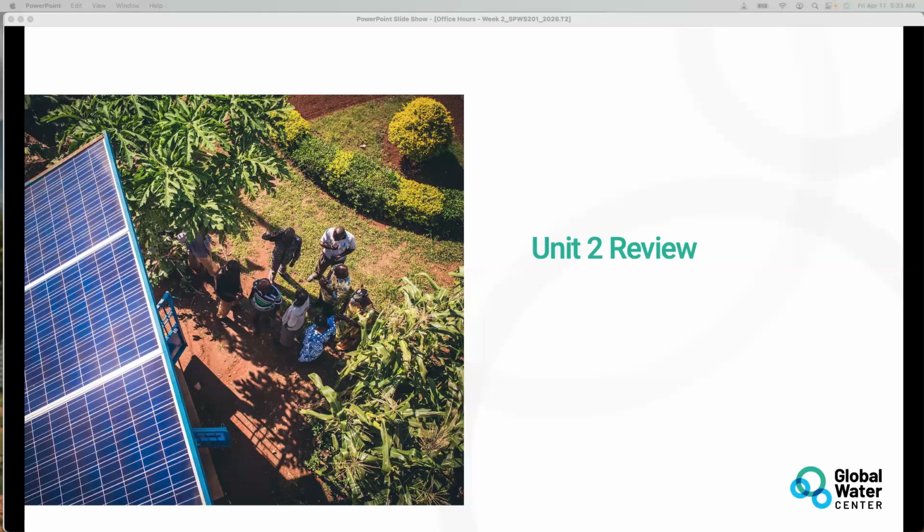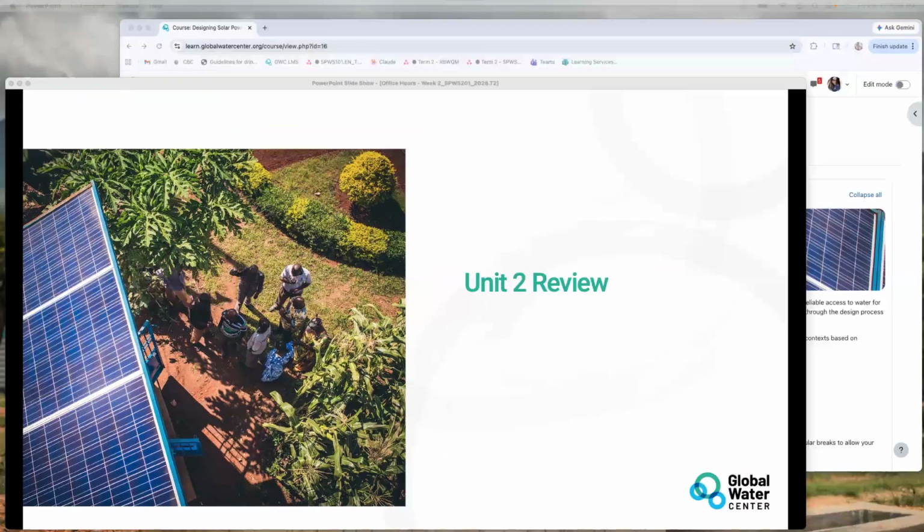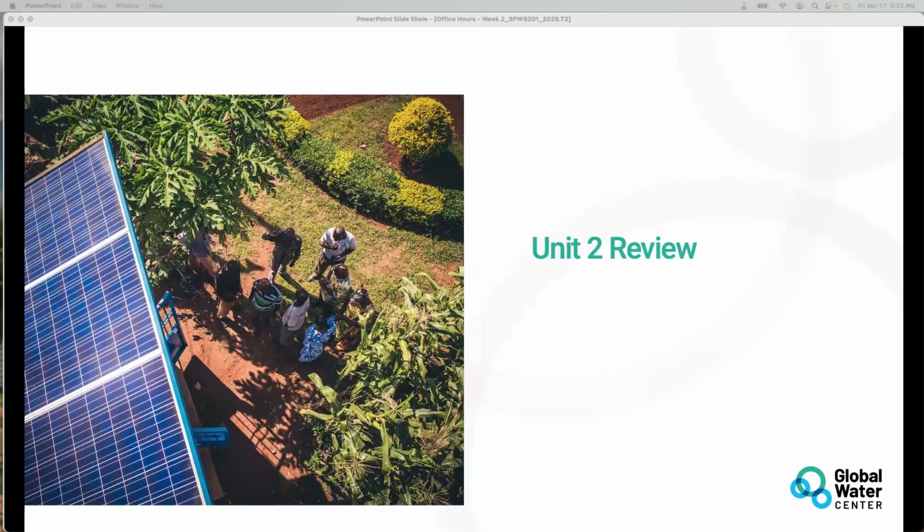But the casing is really written simply as a casing, the casing where the pump is positioned. Is it blind casing or screen casing? In my knowledge, we never position submersible pumps on screen casings. We always position it in blind casing.